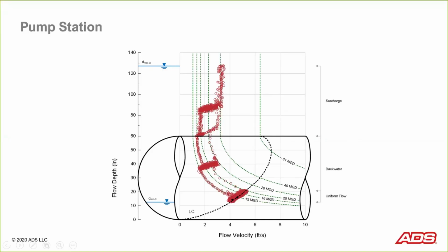And we will stabilize here. And then if we start to get more flow coming in from that, it will start to accumulate because we're maxed out on the capacity of this station, which is 40 million gallons per day. Eventually, if the flow rates abate, that 5-pump combination can pull the flow down. It'll hold here. It'll pull it down, hold here, pull it down, hold here, and it'll pull it down again until we're back to normal.